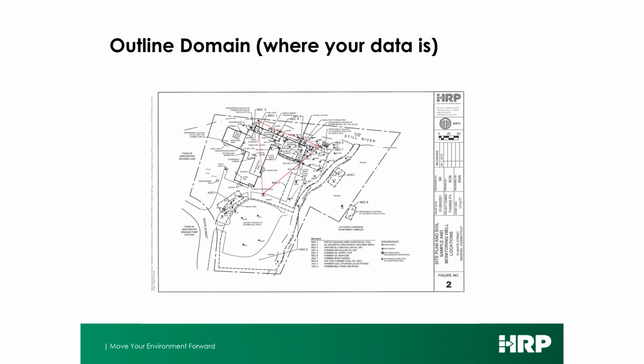And not consequentially there, it defines basically a triangle because all the wells are in a row along the river. Probably not a great mystery here as to which way the groundwater is going to go on this site, even without knowing what the topography is on it. We'll just say that the parking area next to where MW1 is the elevated spot on the site. So yeah, it's not only got the river bounding it, but topographically it goes to the river. So this was basically a no-brainer when you got there, where it was up and down gradient.